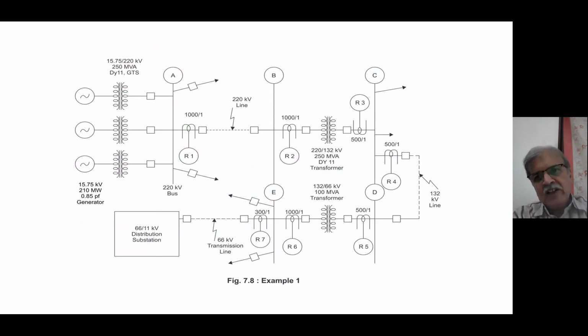First line 220 kV, some 66 megawatt; second line 132 kV; and third line 66 kV, some 22 megawatt. That is the full maximum rated power flowing through the lines, and that power already considers 10% overload. That's what we assume, so we do not have to multiply by that 1.1 factor. We may forget, because we want to go fast.